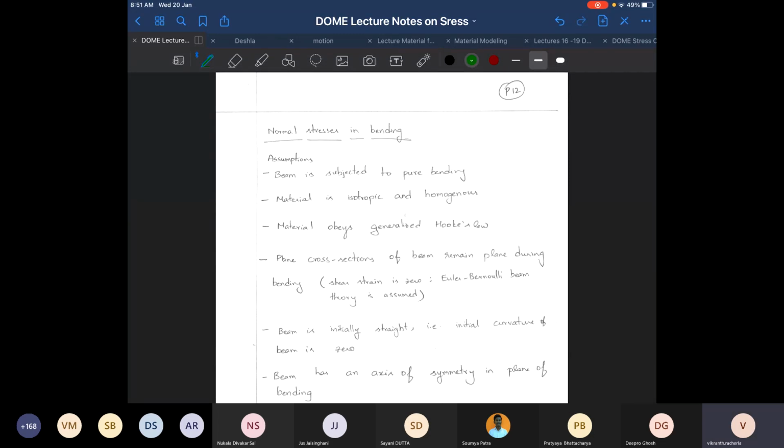What is the relation for bending stress, or normal stress, from bending moment? My by I. So I can write sigma equals My by I. I need to know the bending moment at that point, the distance from the neutral axis, and the corresponding moment of inertia. What is the relation for shear stress?